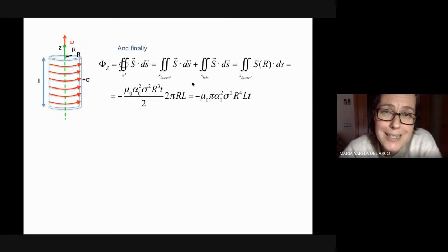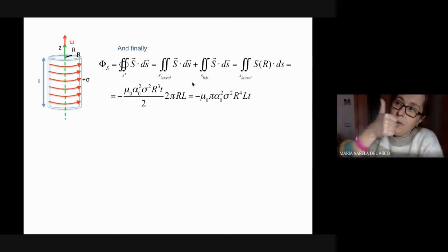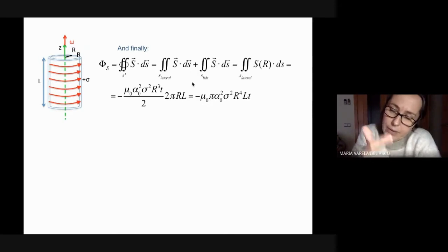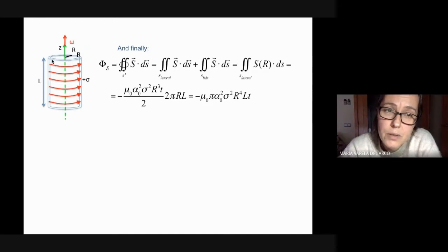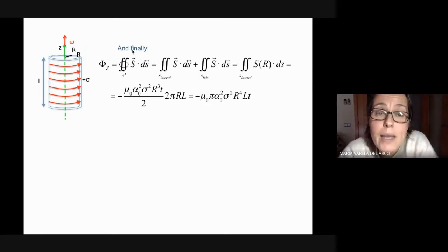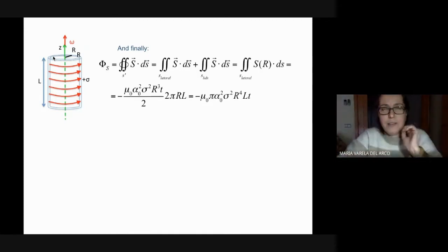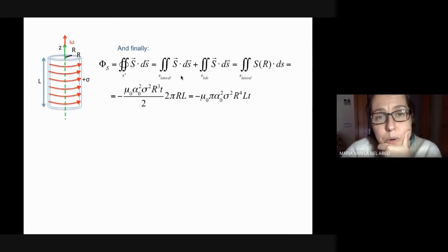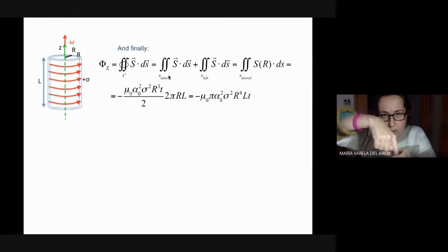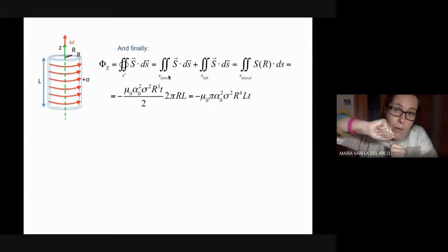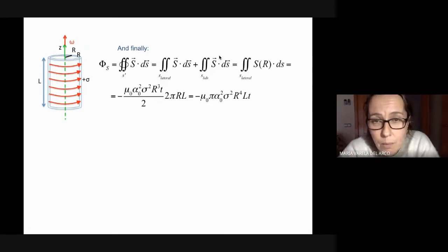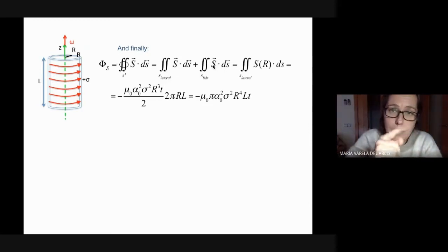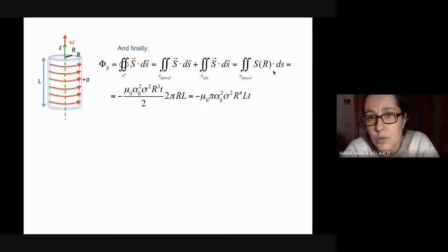Anyhow, finally, we also have to check the second term, actually the third term. We already have the mechanical power is 0, the electromagnetic power, we have it, and now let's check the flux of the Poynting vector on the surface of interest. There are two capital R's there. I'll fix that on the slides because obviously there is one R too many right there, my bad. But anyway, the flux of the Poynting vector on the inner surface of the cylinder, just inside, in other words, on the empty surface that sort of touches the cylinder inside, is going to be a sum of the flux of the Poynting vector through the lateral surface plus the flux through the lids. However, the Poynting vector is radial, so the lids do not contribute to the flux because S is radial. dS would be like u_z or like minus u_z for the bottom lid. The dot product is 0. So all I care about is the contribution through the lateral surface.